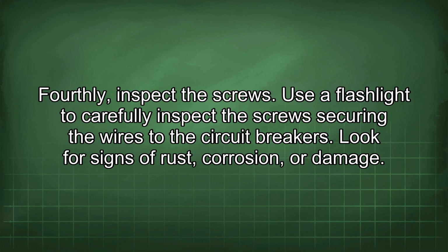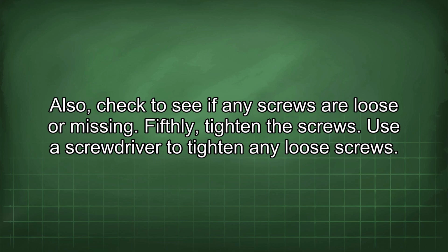Fourthly, inspect the screws. Use a flashlight to carefully inspect the screws securing the wires to the circuit breakers. Look for signs of rust, corrosion, or damage. Also, check to see if any screws are loose or missing.